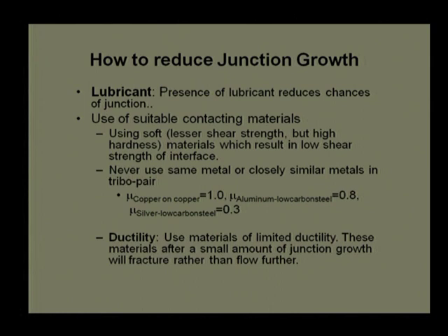That is why many times we use molybdenum disulfide between the two contacting surfaces, which has very low shear strength. Molybdenum disulfide can sustain high compressive load, but its shear strength is negligible. Shear planes will simply move under some load.